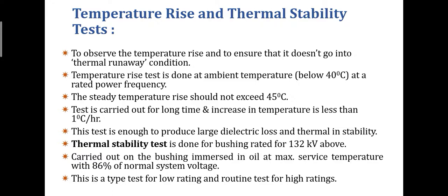The thermal stability test is done for bushing rated for 132 kV and above. It is carried out on the bushing immersed in oil at maximum service temperature with 86% of normal system voltage. These all come under the thermal stability test. This is a type test for low ratings and a routine test for high ratings.